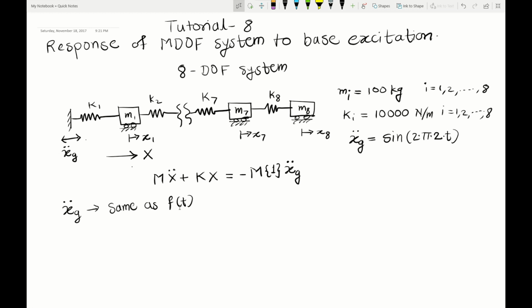One more thing that I am going to do here is a difference in the modeling aspect. If you remember, we had a segment like this, and I used to create nodes on it and then join them. So instead of doing it that way, I will create the first element itself first, and then I will use multi-translation in the Salome interface and use that multi-translation to create all the remaining elements.